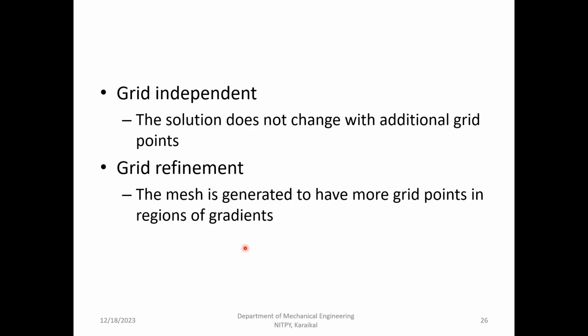In grid refinement, knowing the physics, you know at what points it is going to be crucial for you. So if you have a burner, just the exit of the burner will have all the combustion taking place. So that must be refined to fine, and the other regions can be coarse. That kind of study you can implement before you go with Fluent. That will help you a lot. We'll look at an example of this.